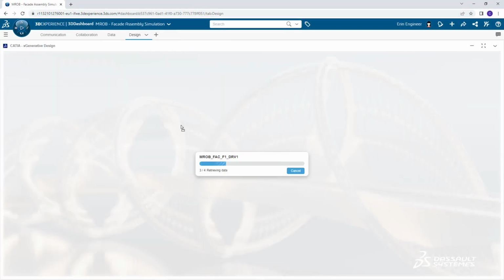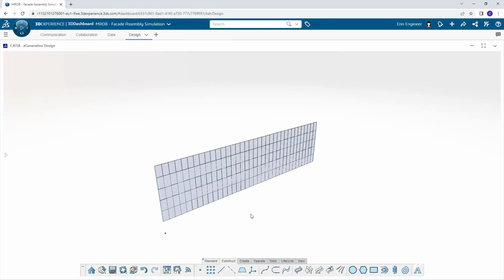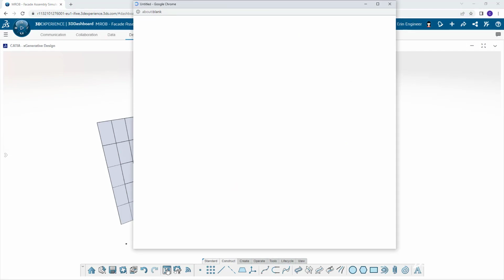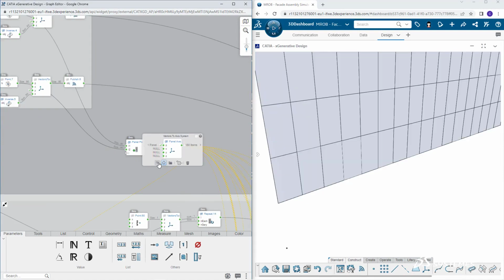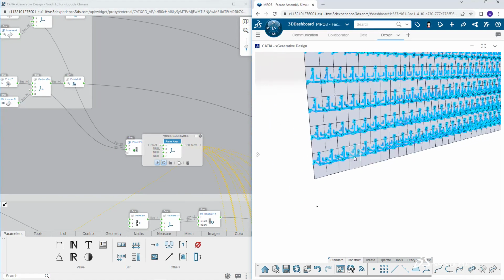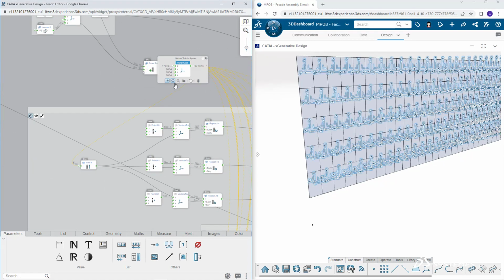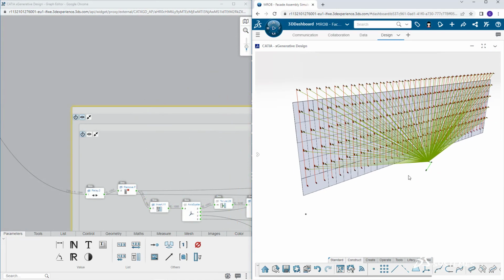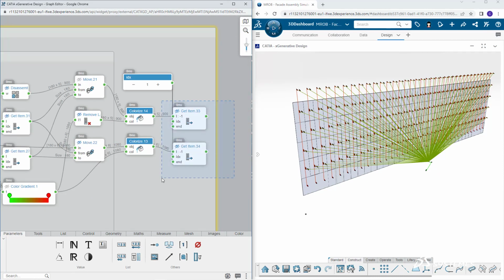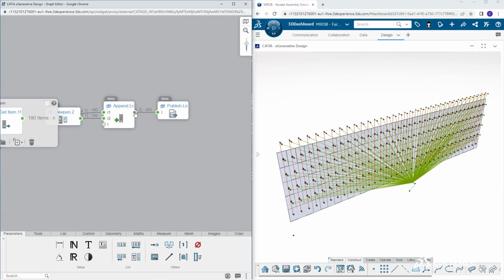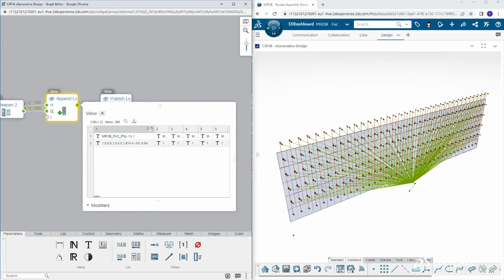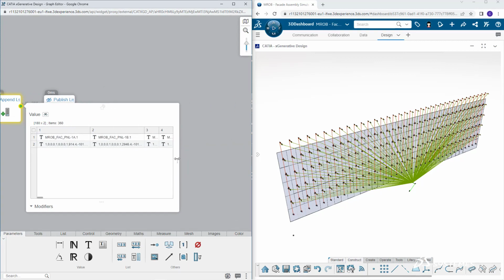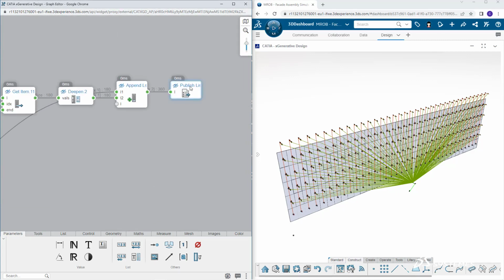The facade production engineer wants to explore how to create these tracks automatically. So they open the Xgenerative Design model. In this model are defined the panel locations and types as access systems. And then they've defined a series of tracks within Xgenerative Design, which are visualized, showing the start and the end of each track. The final output from Xgenerative Design is a list which includes the panel name in order and all the access systems as a string, which will be interpreted in the final model.